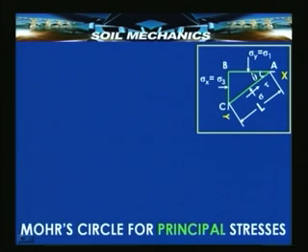Let us take sigma y to be greater than sigma x, and then sigma y becomes the major principal stress. So, this is equal to sigma 1. On the other hand, BC automatically becomes sigma x, or the minor principal stress acting horizontally on the plane BC, and correspondingly, if you take a plane CA at an angle theta with respect to the horizontal or major principal stress, then the normal and shear stresses on this plane AC, sigma and tau, can now be computed in terms of sigma 1 and sigma 3, either by Mohr circle or from the rigorous expressions.